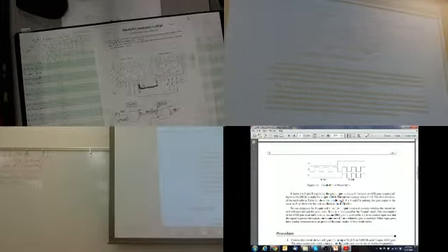The first thing you probably want to do is turn this on, connect these two together, and see if you can get anything on the output. That's one of the first steps. You think you've got it built. So all you do is just connect this part. This is called the witch's hat. It comes off. It's used for probing, but we're not going to stick that in there, because as soon as it gets bent over, that's a $200 probe coming to the end.